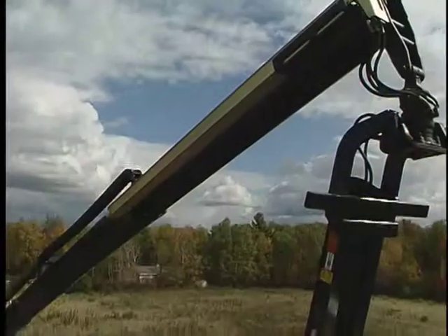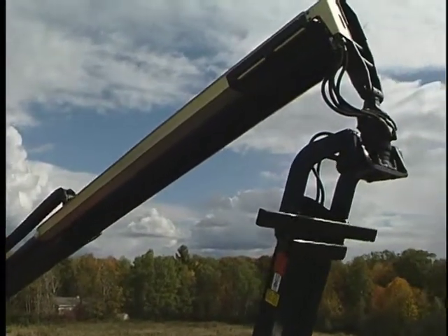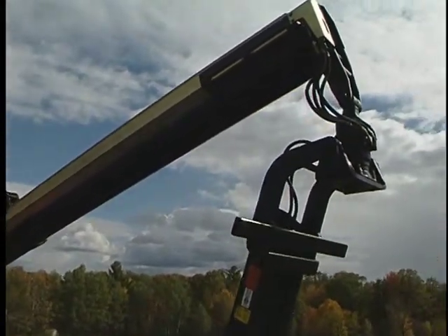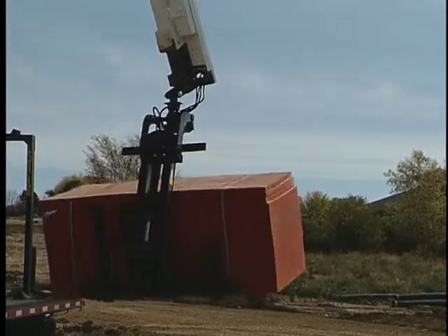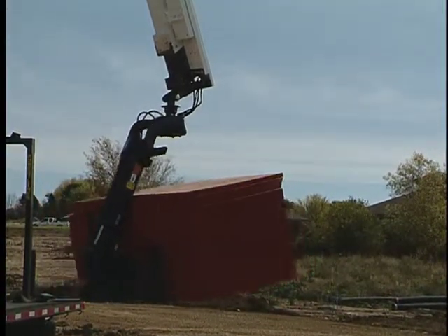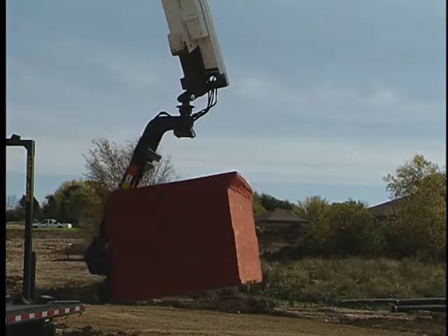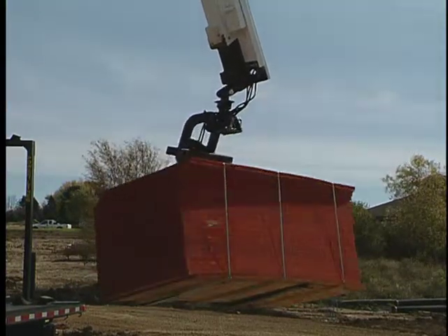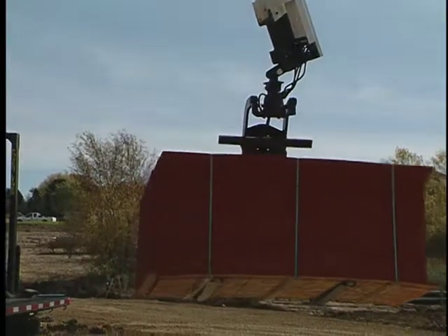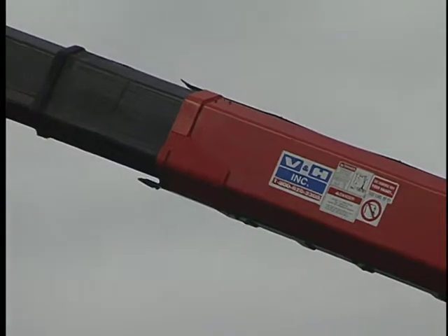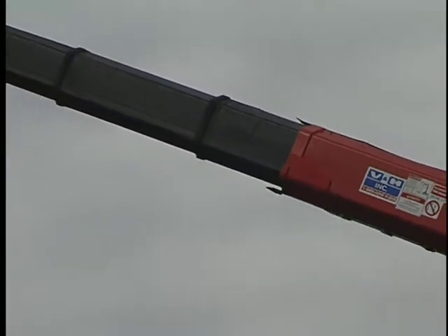Once you are near the delivery position, extend the boom until you are at the proper height. Rotate the fork until the load is correctly positioned to enter the delivery zone opening, which is typically a window, a door, through studs, over framing, or to the ground. Now you can carefully extend boom to the delivery zone where the helper waits.